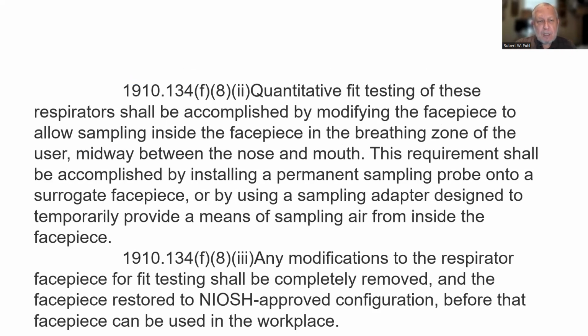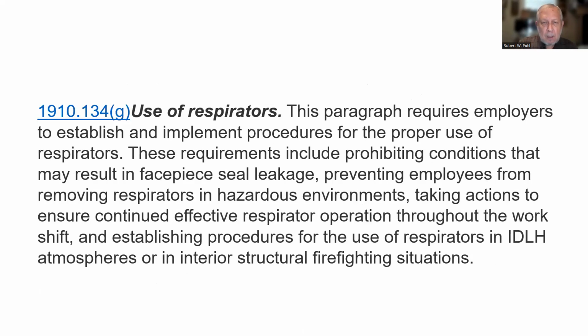Quantitative fit testing of these respirators shall be accomplished by modifying the face pieces to allow sampling inside the face piece in the breathing zone of the user, midway between the nose and mouth. This requirement shall be accomplished by installing a permanent sampling probe into a surrogate face piece, or by using a sampling adapter designed to temporarily provide a means of sampling air from inside the face piece. Any modification to the respirator face piece for fit testing shall be completely removed and the face piece restored to NIOSH approved configuration before that face piece can be used in the workplace.